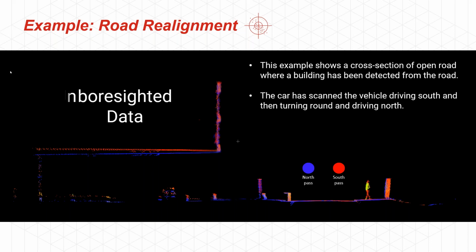So if we now boresight this data, you can see that they overlap as they should, and there's no divergence as the points get further away. So you can survey the same objects, again, adding to your point cloud instead of ruining your point cloud.